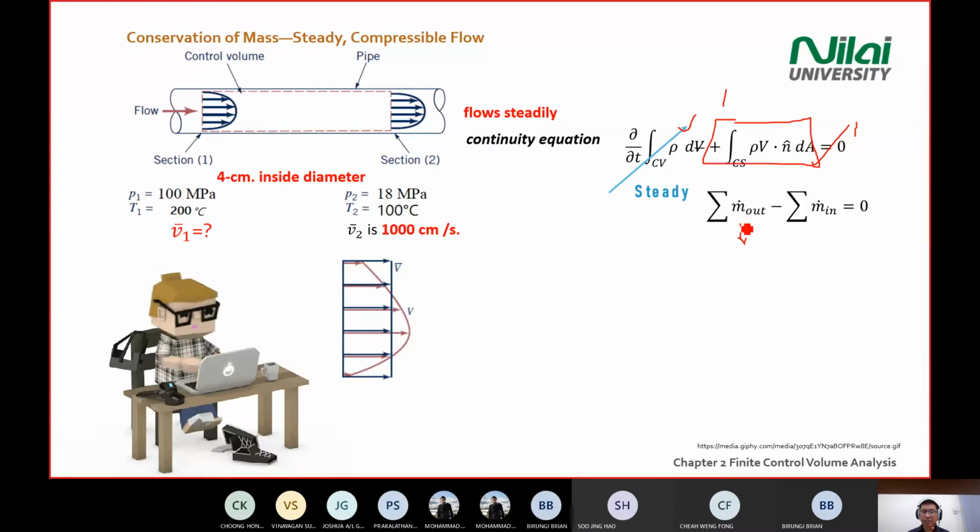You will see the standard procedure here. Always have the flow, always have the procedure. Step 1 do what, step 2 do what, step 3 do what. What will change in the question is all these parameters and sometimes the shape. The first thing, you see steady flow, call out the continuity equation, cancel one of the components because it's steady, and then continue with the second component, m dot. So you have rho A V, with out equal to in.